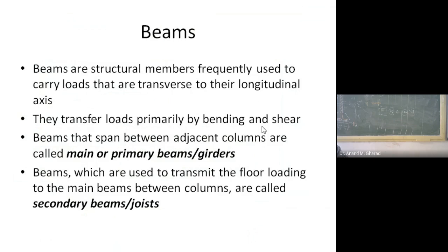See, whenever we talk in terms of a beam, it is resting on two or more supports. Because you can say it may be a simply supported beam or a continuous beam or fixed beam. So what do you understand by all these things? That there are some supports associated to the beam. Because of the presence of the supports, there are reaction forces which are developed. In addition to reaction, if it is fixed, moment is also developed, isn't it? So at the ends, particularly where supports are available, you can experience shear force also. Okay. So talking in terms of beam as such, it will not only carry the bending part, it will also carry the shear force. Okay.